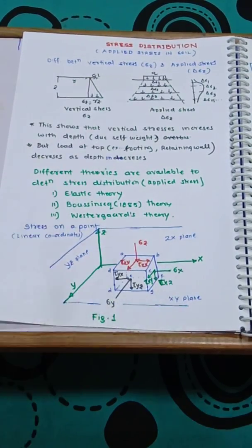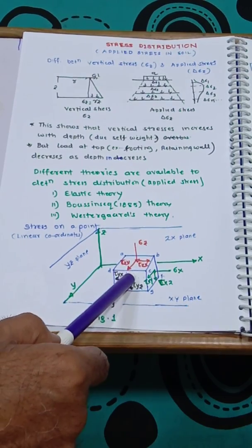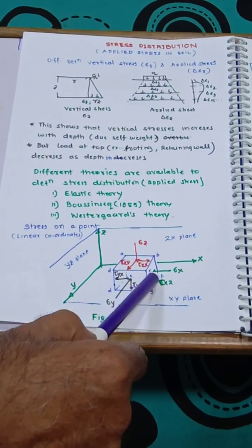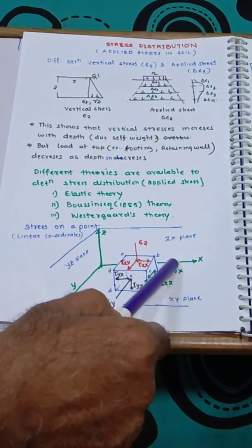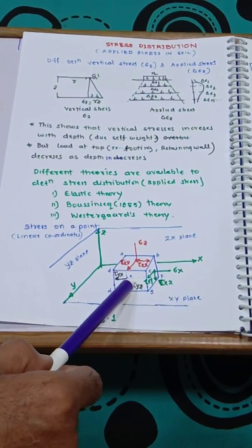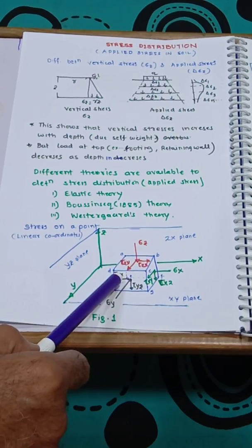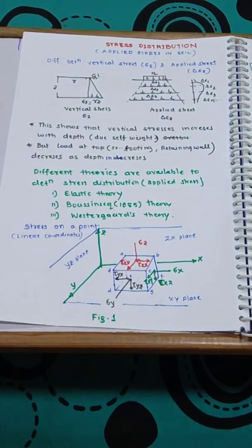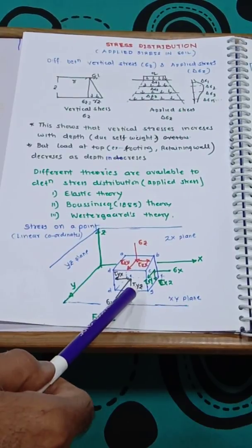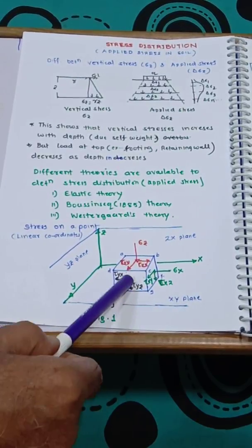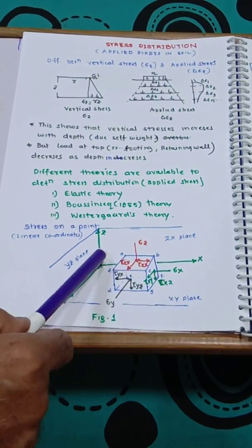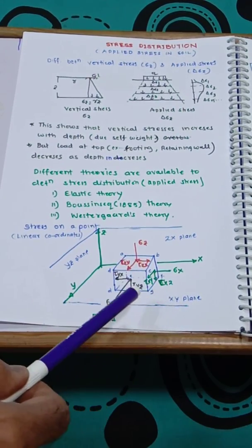That's why it is sigma y. Now for the shear stresses, if I take the horizontal shear stress, either in this direction or this direction, this is parallel to the x direction. Therefore, it is at distance y and parallel to the x direction. So it is tau yx. Similarly, a downward stress is again at perpendicular distance y and parallel to z. So tau yz.